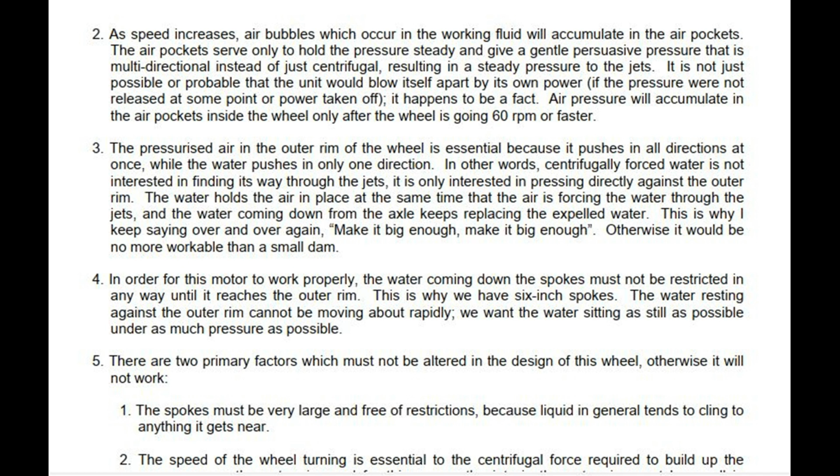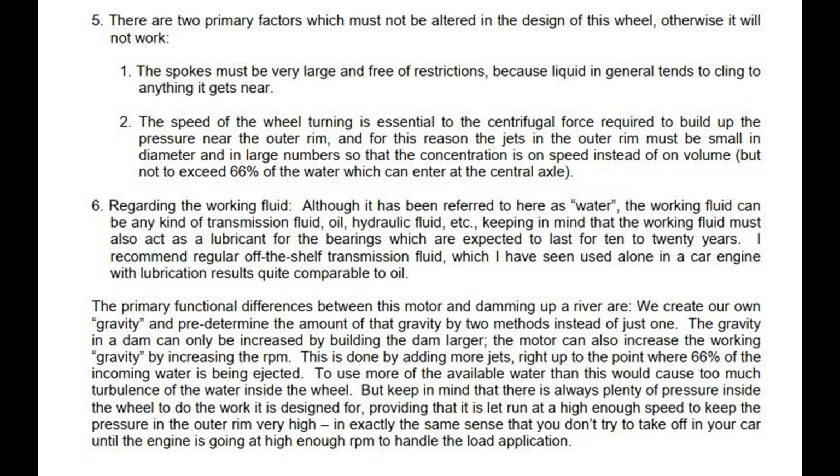5. There are two primary factors which must not be altered in the design of this wheel, otherwise it will not work. 1. The spokes must be very large and free of restrictions, because liquid in general tends to cling to anything it gets near. 2. The speed of the wheel turning is essential to the centrifugal force required to build up the pressure near the outer rim, and for this reason the jets in the outer rim must be small in diameter and in large numbers so that the concentration is on speed instead of on volume, but not to exceed 66% of the water which can enter at the central axle.